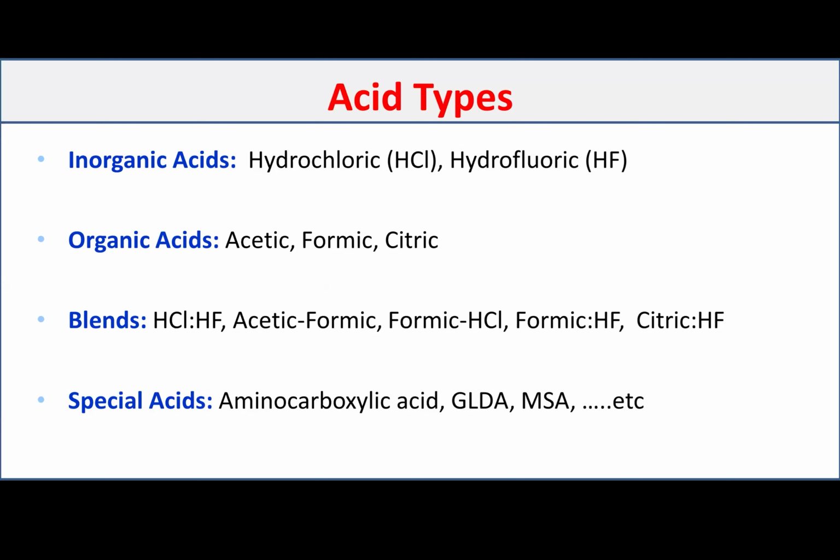The second one is hydrofluoric acid, which is the main acid for sandstone formation. When you have a sandstone treatment, you must have some sort of HF treatment. It can be applied directly as HF, or you have some sort of chemical that will be converted downhole to HF, because that's the only acid system that is able to dissolve silica and the clay minerals. Therefore, for sandstone acidizing, HF acid is the main acid that we are using.